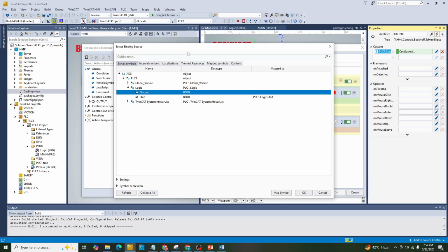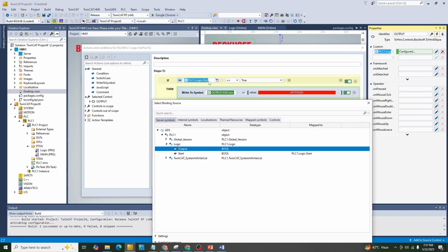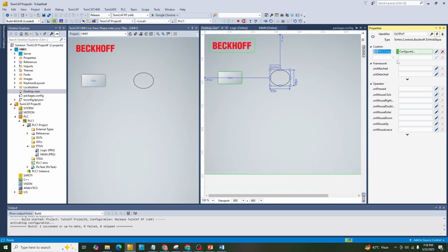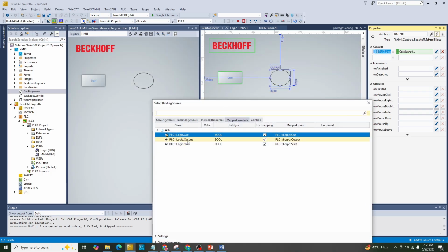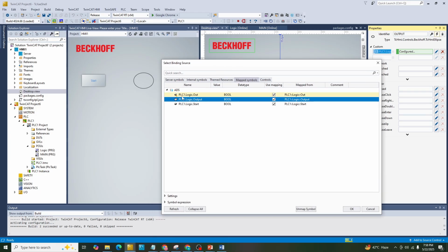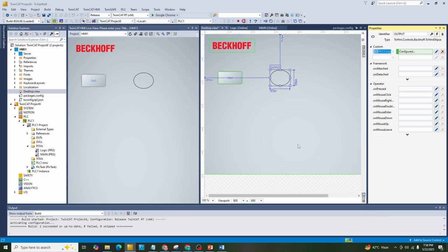Oh, perfect. The problem was this is out, but my original tag for the output is output basically. So I will create a data binding with output, click OK. I need to use this output instead of out, because out is not a tag here. So simple this configuration.